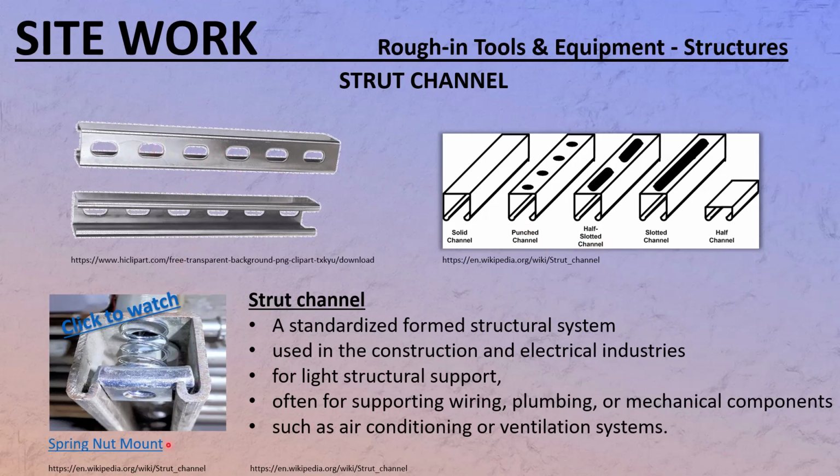Now, how do you mount the threaded rod in that? There also is something that's called a spring nut mount. You just install it, it's a spring-loaded nut. See, there's a thread here, and you put it on top of that opening there, the slot. And once you start turning in the threaded rod, it can just go as far as you want and so on. They're spring-loaded nuts, so you just install that.